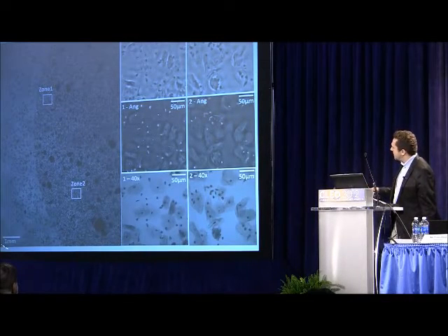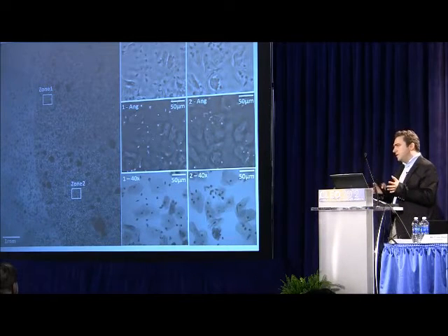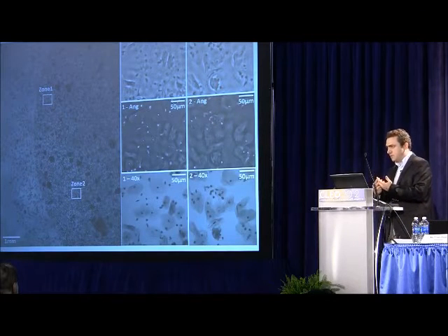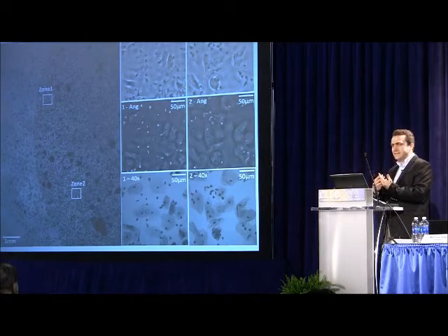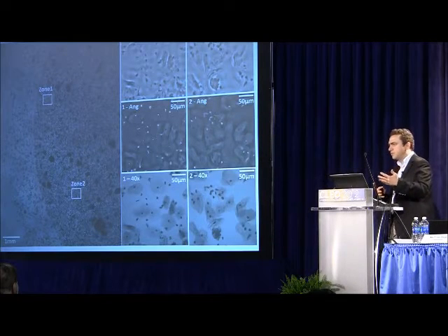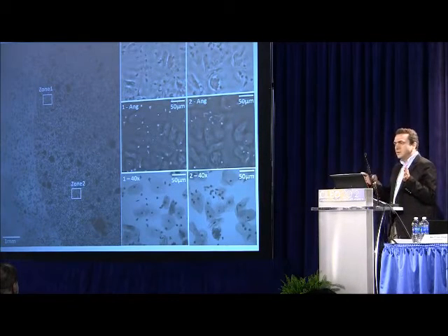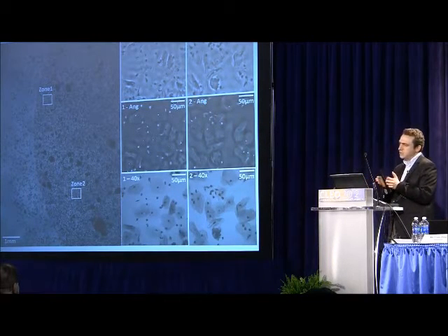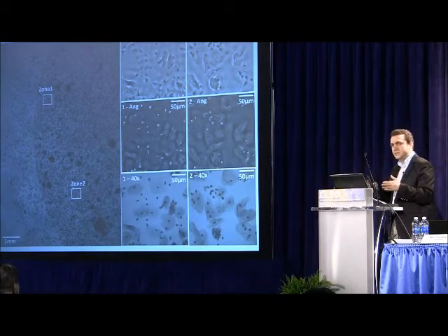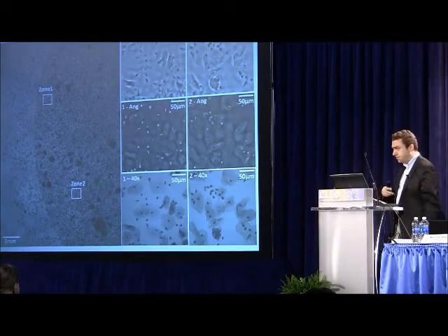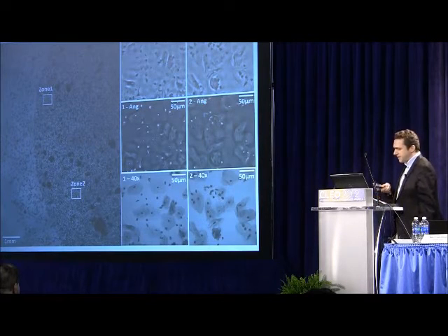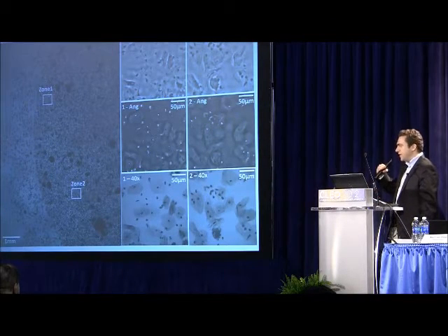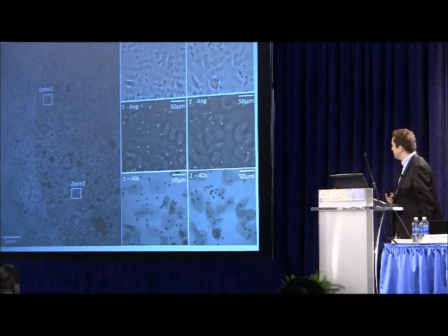And in this case, the field of view is around 30 millimeters square. So the field of view scales with the sensor. That's kind of a unique feature of lens-free computational imaging. It can follow Moore's law qualitatively in the sense that next generation sensors, which would be 15 megapixel, 20 megapixel, would not trade off anything in our design. And it's going to enlarge the field of view without degrading the resolution. And sometimes it's going to improve the field of view and resolution at the same time, depending on the design of the CMOS imager. And that's where you can really follow, with your microscope and without changing your reconstruction, a trend which improves the field of view and resolution at the same time.